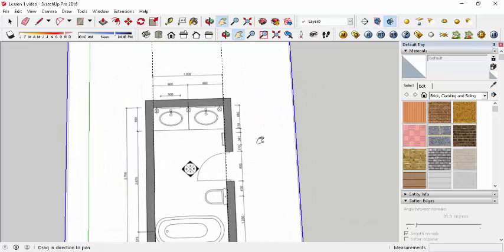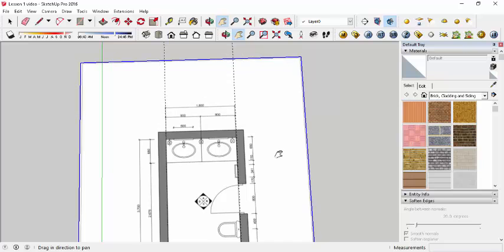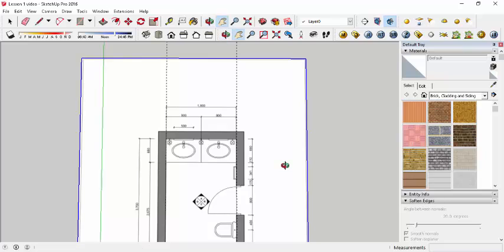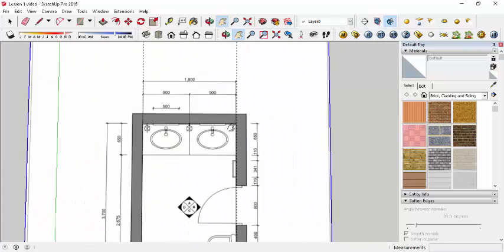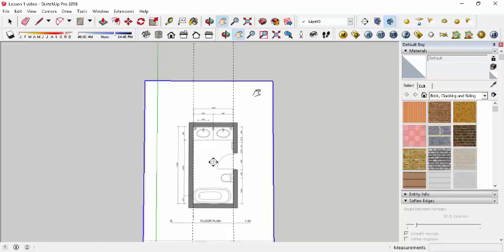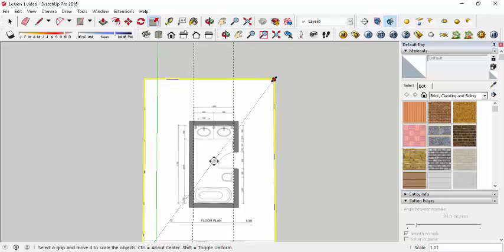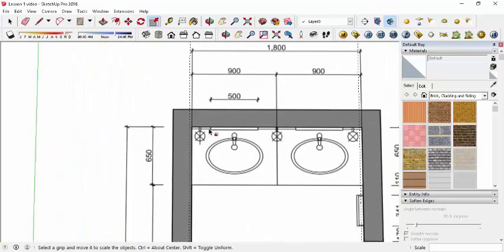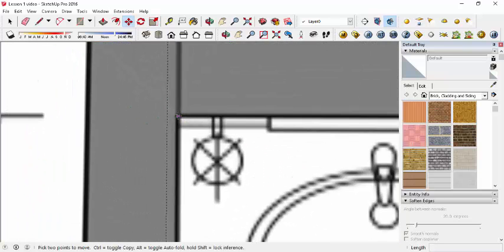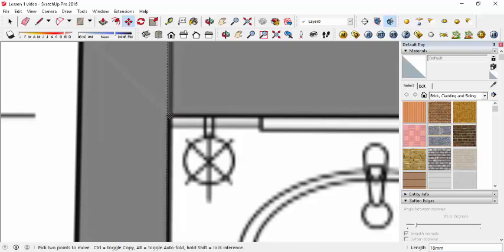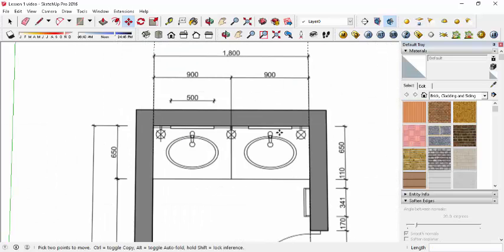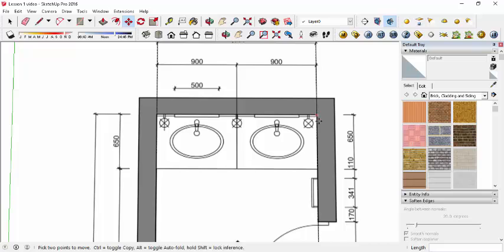Okay, that's a tiny bit smaller. We don't have to have the exact measurement because we're working on 3D, and what 3D does is just to have a visualization. It doesn't have to be exact. This is not construction drawings, so it's okay if it's a little bit off, but we can still rescale it. So hit S again and then drag that. Maybe this one is a bit better, so let's move this again. Click on M, move that to the guideline. Okay, now that's aligned.